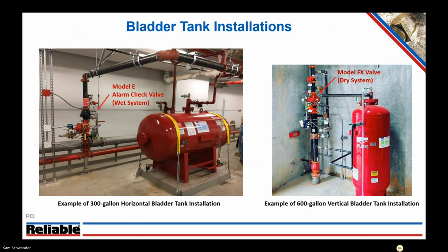These proportioning devices are modified Venturi type devices. They're using the flow across the proportioner to have a lower pressure drop area that's going to take up the friction loss in the concentrate piping. So that is one downside of bladder tanks. We want to keep them relatively close to the point of injection here.